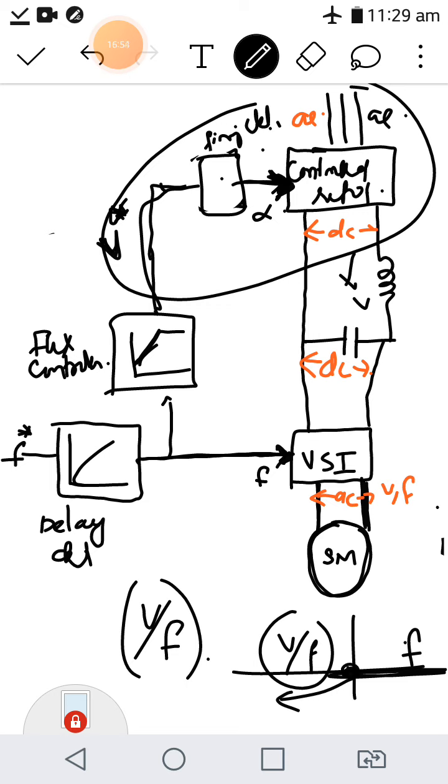So this is actually the true synchronous mode of operation. In this true synchronous mode, the stator frequency, the supply frequency, is controlled from an independent source. Here, the frequency from its initial to the desired value is changed gradually, so that the difference between synchronous speed and the rotor speed is always small. And this allows the rotor speed to track the changes in synchronous speed. And when the desired synchronous speed is reached, the rotor pulls into step. And this is what is happening in this drive.